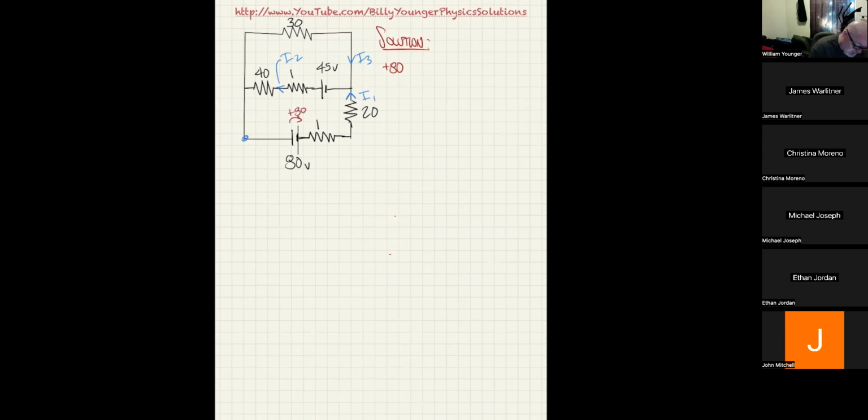And then I'm going to go minus 1 ohm times I1 minus 20 ohms times I1. So instead, I'm going to say minus 21 I1. Everybody see why I did that? The 1 and 20 are in series, so they just add.